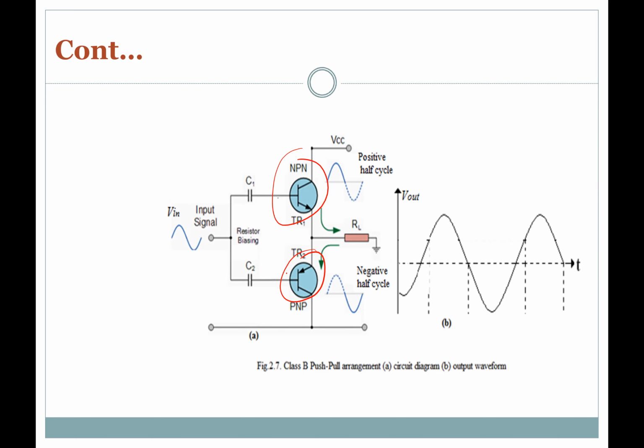In some literature you would see it labeled as the push-pull arrangement. These complementary devices are used to each amplify the opposite halves of the input, that is the positive and the negative halves, which are then recombined at the output. So at the end of the day, you would now get both the positive half cycle and the negative half cycle. Now, push-pull amplifiers use two complementary or matching transistors, as we have already mentioned.